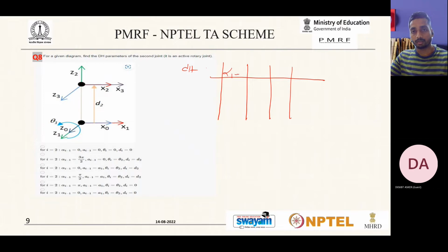So we have alpha i minus 1, then a i minus 1, d i, theta i. The alpha i minus 1 and a i minus 1 are measured with respect to x i minus 1, and d i and theta i are measured with respect to z i. Great. So let us look at each of the joints. So for joint 1, let us look here. So we have Z1 here.